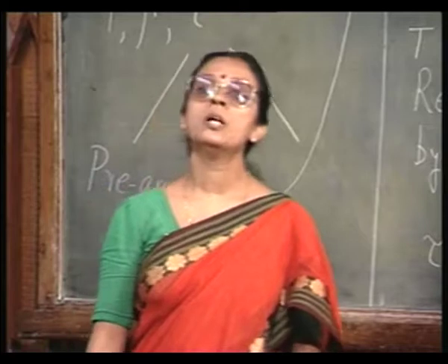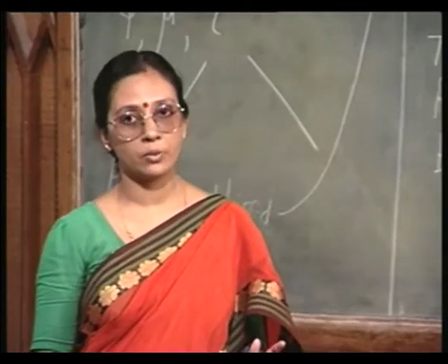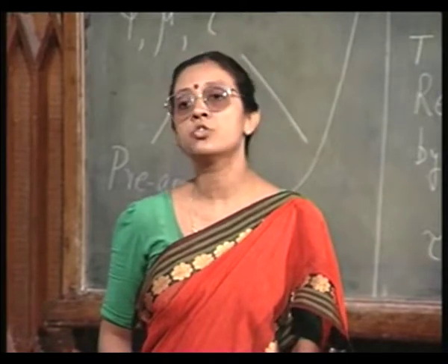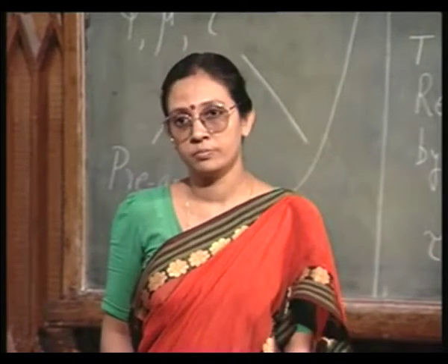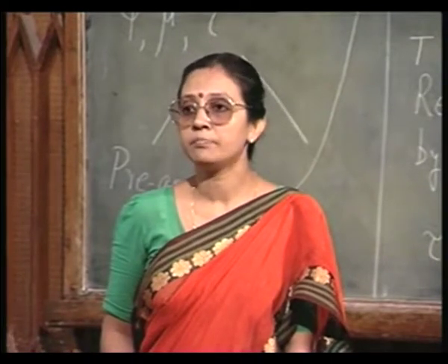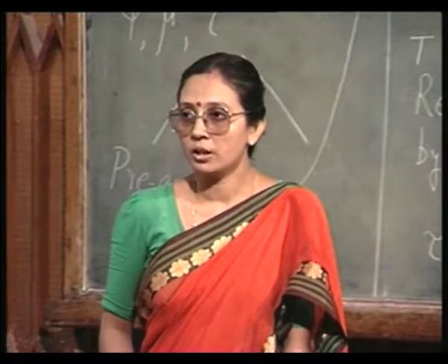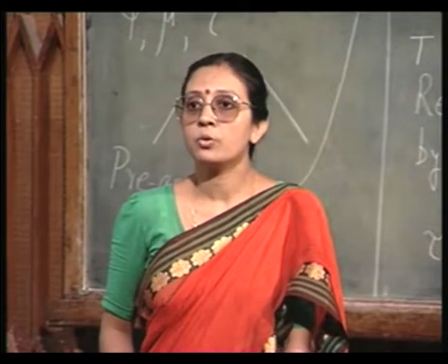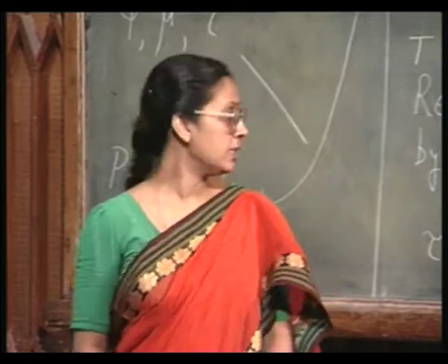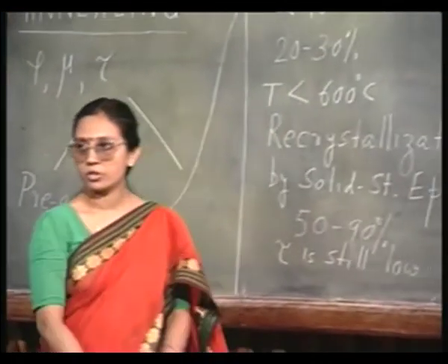So, now depending on what your requirement is and what your obligations are, you can choose your annealing schedule. If you can live with low lifetime, and on the other hand you would like to maintain the annealing temperature and time low, then this phase would be sufficient.